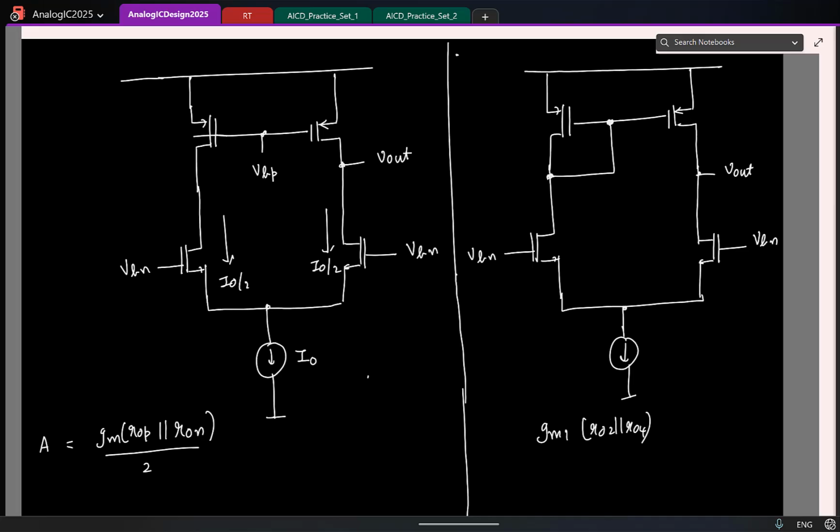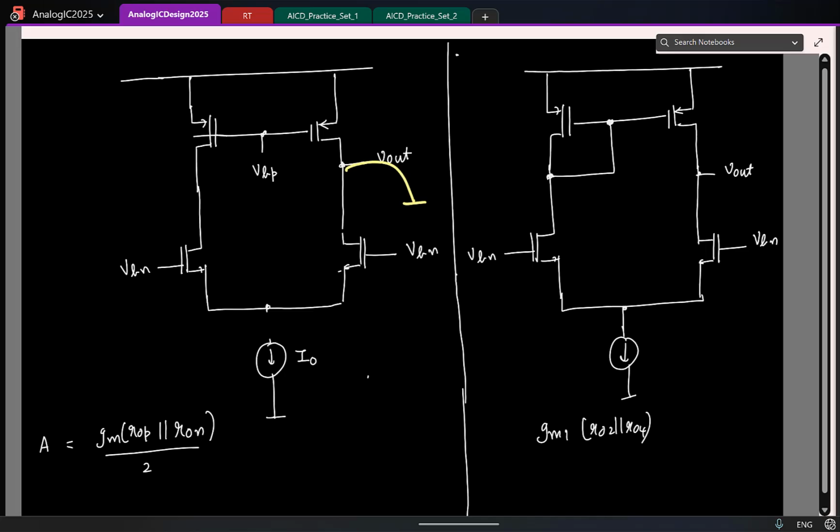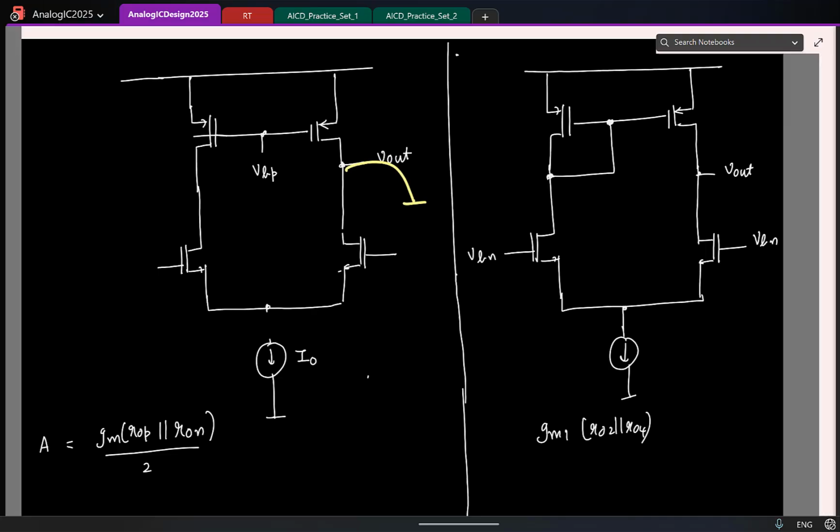Okay, so let's try to calculate the short circuit gm for this fellow. If you try to find the short circuit gm, again, current source is going to be open. So let me open this. So I'm going to short circuit this. Again I'll apply the same thing. V1 and V2 will be there, and again by now you should be able to tell me what is Vx. V1 plus V2 by 2. We did it twice already today. So it is V1 plus V2 by 2.